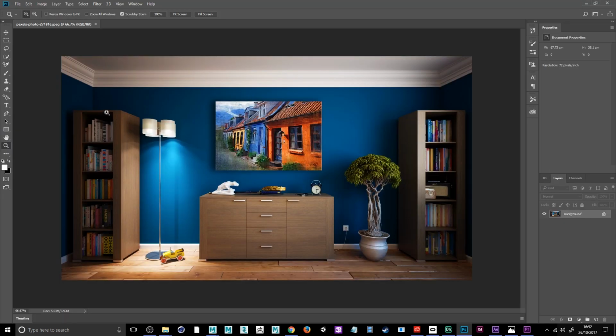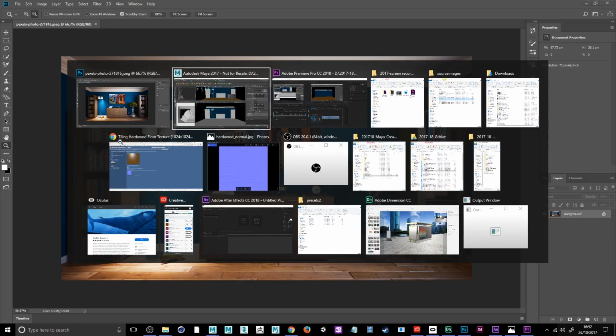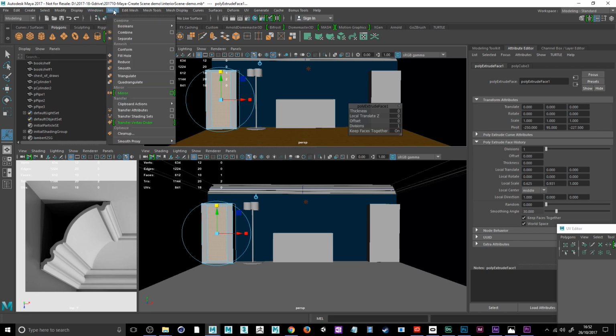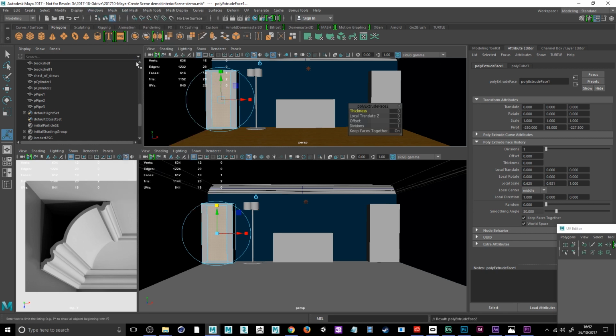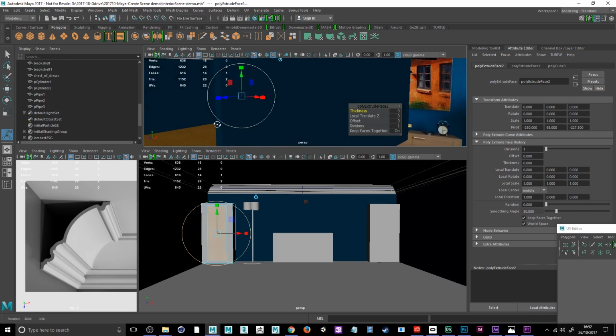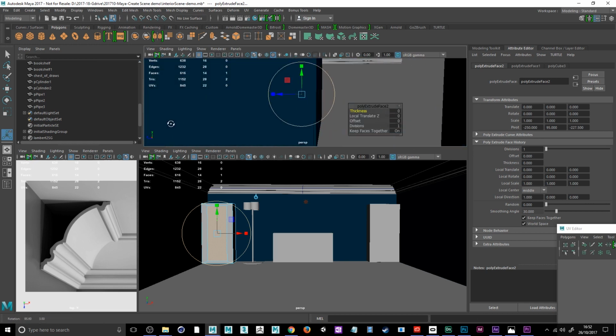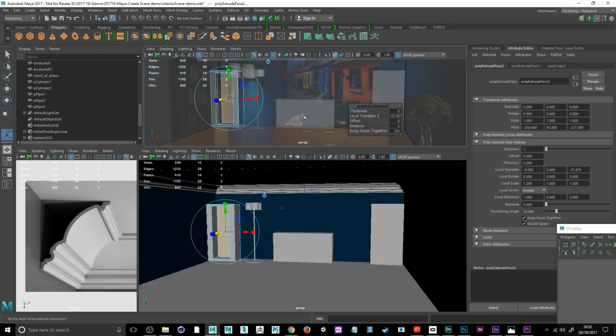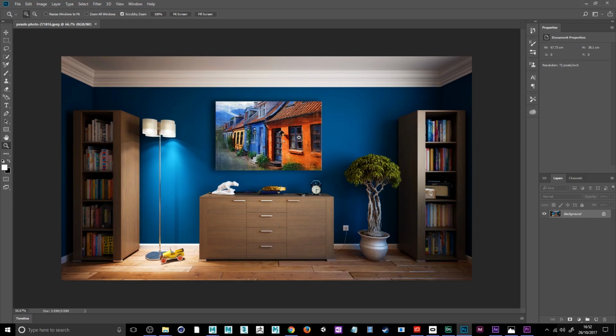So it's going to be small at the top, but it's quite thick and stylized on the edge. So I'll make that thinner on the top, and then once I've done that, I'll do another extrude, and this time I will just push that back. So I can turn on the X-ray and just push that right back, and I can see how that's fitting in there. So that gives me the basis of my bookshelf.